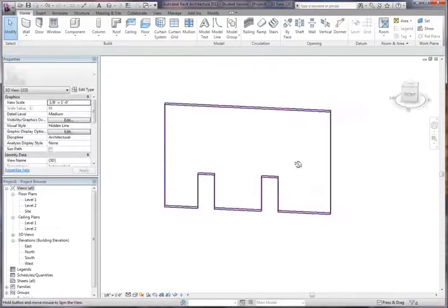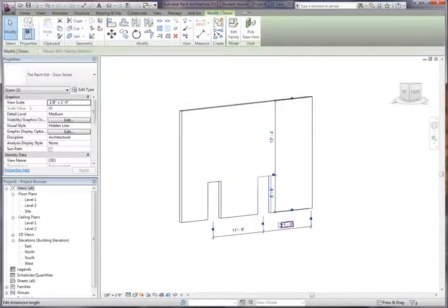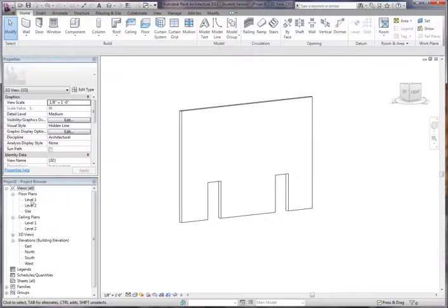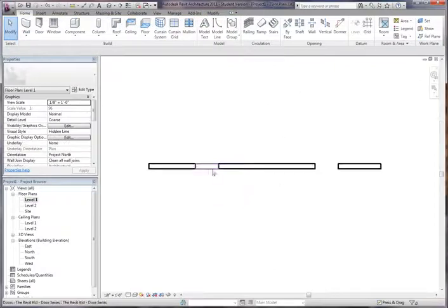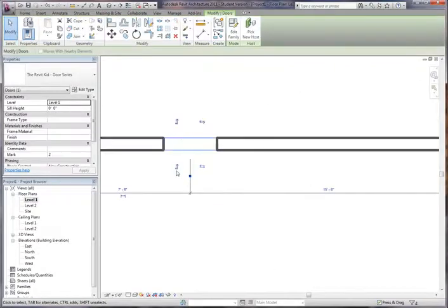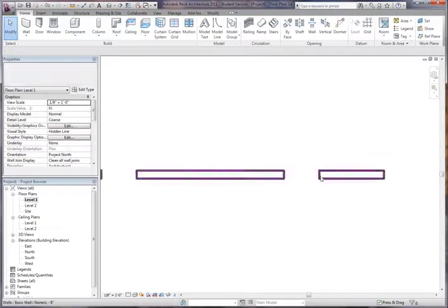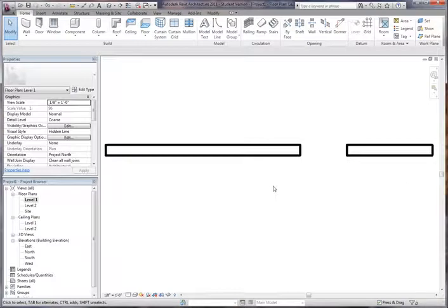So now you can see it's actually cutting the wall. It's doing everything you need. If you move it, if you go on floor plan, you've got your 2 openings here. And these are our controls. So now you can't really see too much what they're doing yet, but once we start adding stuff you can see. So I really want to start very basic now, so that's how you make an opening to a door.